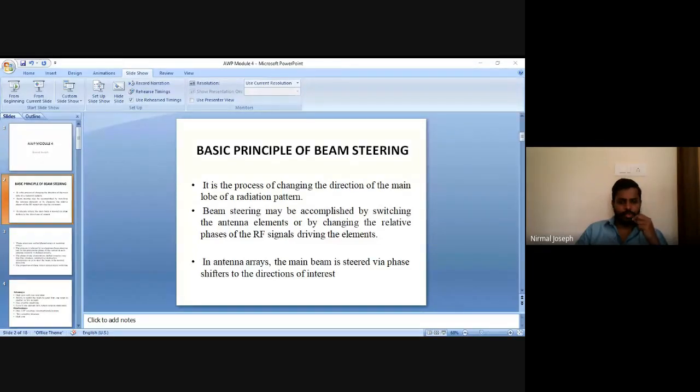A 180 degree phase shift will be provided by the transistor. Then the remaining 180 degree phase shift should be provided in order to meet the Barkhausen criteria. Okay, A beta equal to 1, or total phase shift equal to 360 degree. For that, 180 degree phase shift is already provided by the transistor. Then the rest 180 degree phase shift we have to introduce. For that, what are we doing? We will use RC.